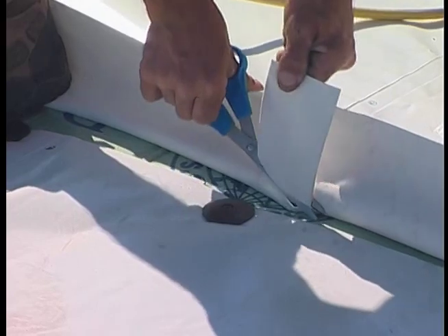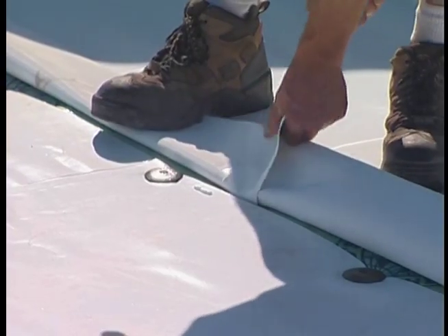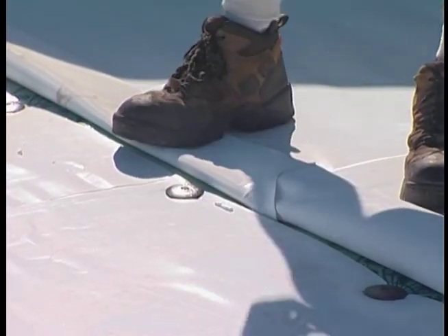If the sheet is installed so that the ends of tabs overlap an adjoining sheet, cut away about 6 inches of each tab from the top sheet. Take care not to cut through the top of the membrane. This is required for proper welding of the sheets.